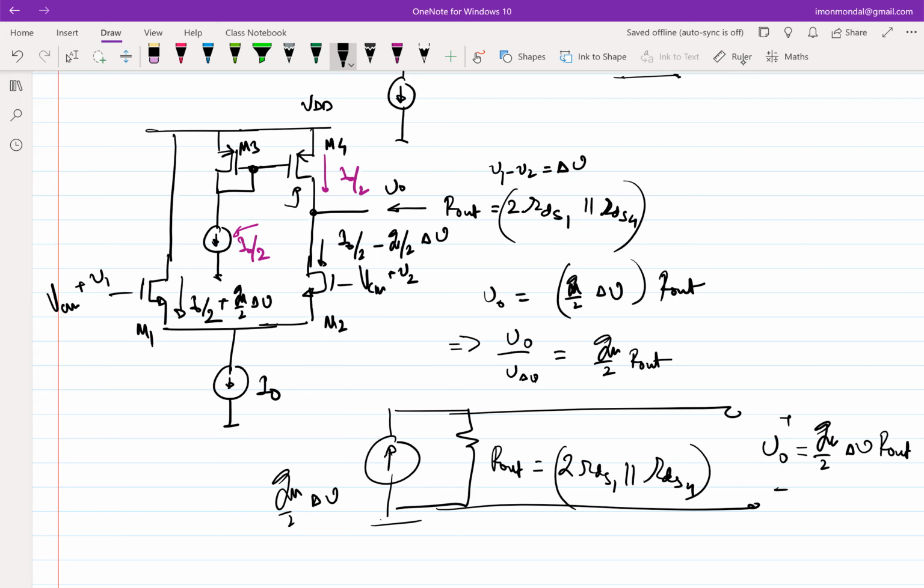And we know how to get this, right? We can mirror it. We have done current mirrors extensively. We can mirror this one. So I'm not showing how you will get the bottom current source. But what about the current source on the top, which gets you I0 by 2? Looking into the circuit, do you see a branch from which I can extract that I0 by 2?